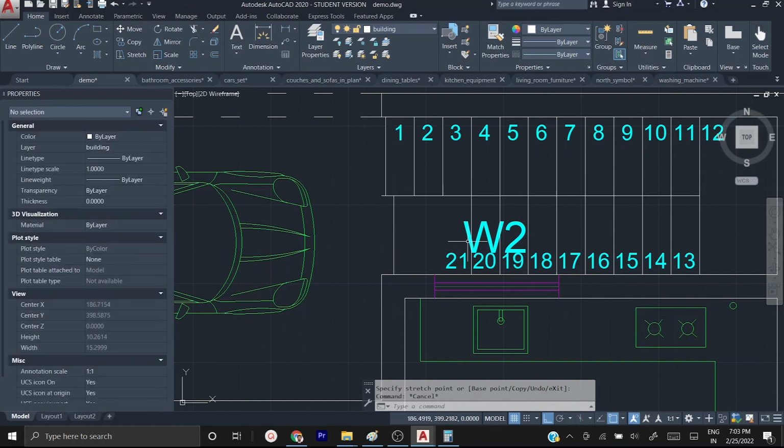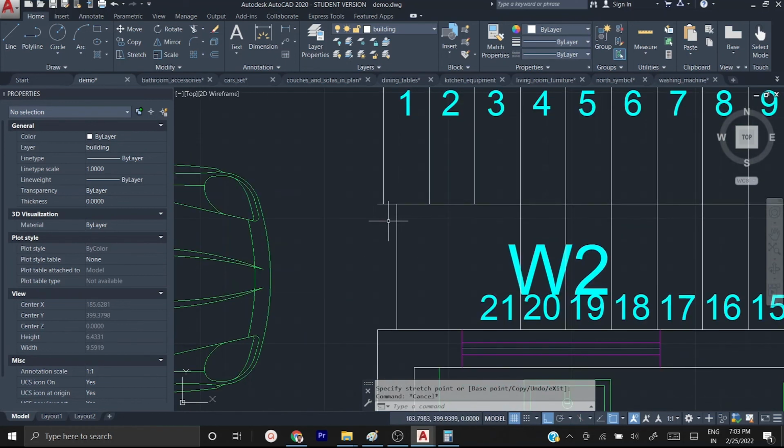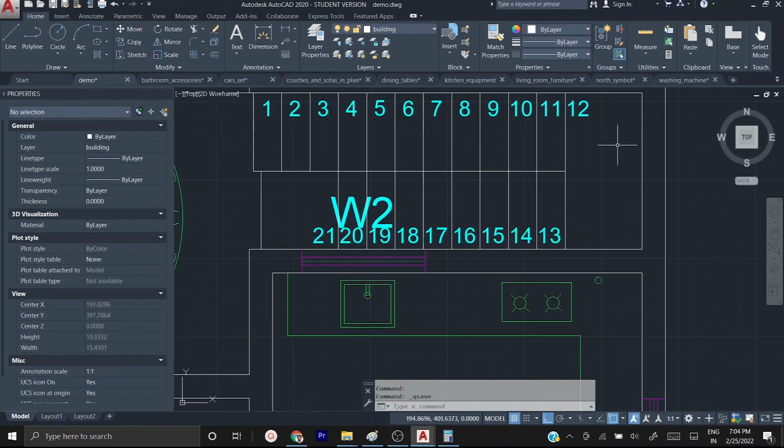Okay, now this is 21st step. Then on the top you got the roof. Okay, so if you put numbering, then that way you can create the stairs exactly. Okay, so now this is my stairs. You can even mention what is your mid landing. Mid landing, this is 2.5 feet wide, then 5 feet length.